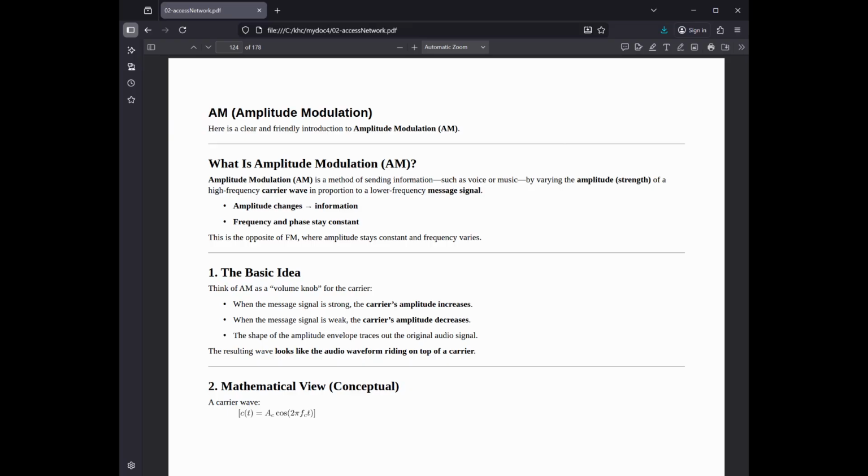amplitude modulation. The core components to create an AM signal: you need three basic elements. Message signal, the actual information, audio, music, or data. It is typically a low-frequency signal. Carrier wave, a high-frequency sine wave that carries the message through the air. It has a constant frequency and amplitude before modulation. Modulated signal, the final output where the envelope, the outer boundary, of the carrier wave matches the shape of your